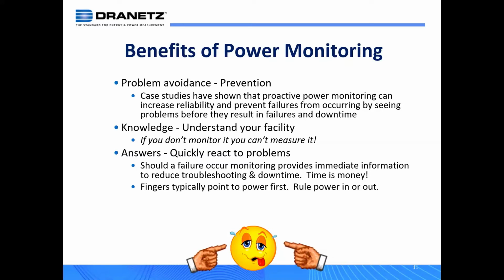They immediately schedule a service call with that UPS module, so they can take it offline on a proactive or structured basis, because they know if they let it go, it's going to just shut off one day, and you don't know if their protection will kick in properly. So that's the problem avoidance. They are preventing the problem by proactively maintaining their systems, using the power monitoring to detect these problems.